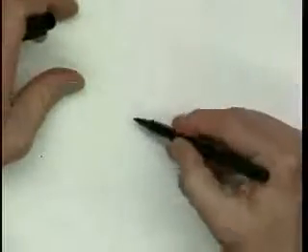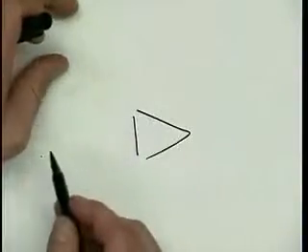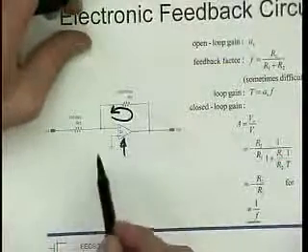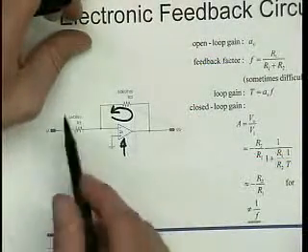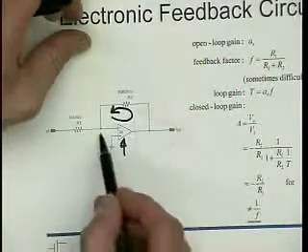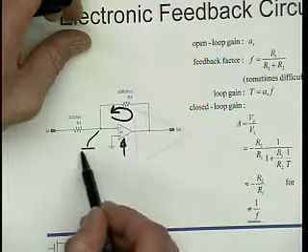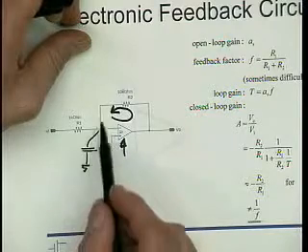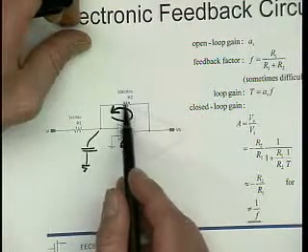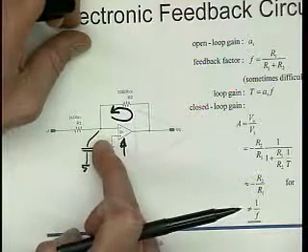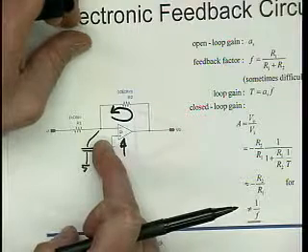It's not necessarily stable then in all situations. For example, I can actually use this circuit here. It doesn't quite have unity gain, but it has a gain of perhaps less than unity. But if I add some capacitance here, and I get it just from the amplifier, then of course I'm getting an additional pole, and so if these resistors are of sufficiently high value, that pole may be a significant additional non-dominant pole.